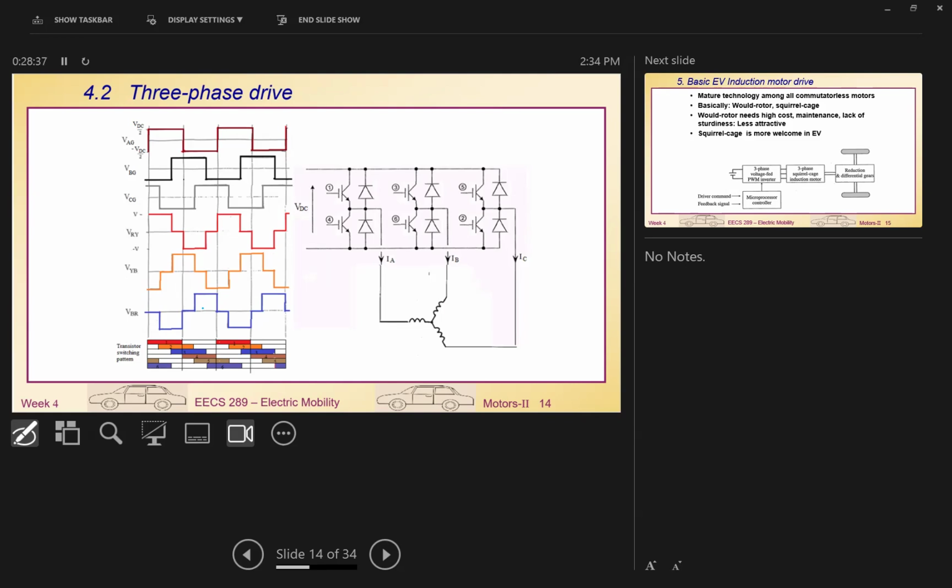So this line voltage is this voltage minus this voltage. That's why for the motor winding between these two, you only understand these two voltages. So A minus this one becomes this voltage. The voltage waveform across these two windings becomes this one, and across these two becomes this one. You can see that this waveform, although a square wave, does have some fundamental component of a sine wave.